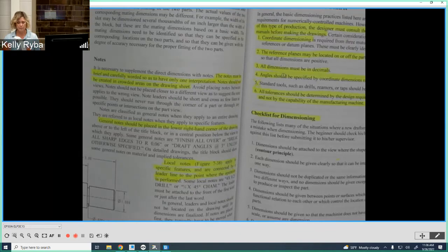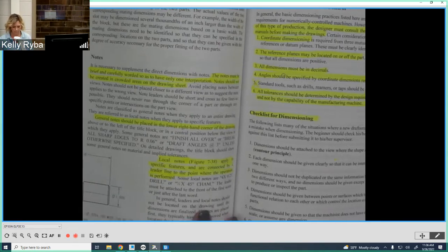So this is where companies sometimes will dictate, this is where we put all of our notes so that we always know on our drawings where to look. Nowhere else. Whether it's to the left of the title block, directly above the title block, or in an upper right-hand corner, a lot of times a company will say that's where we want them. If they don't, the suggested places, like I said, are one of two places: above the title block or to the left. Okay, that's general notes.